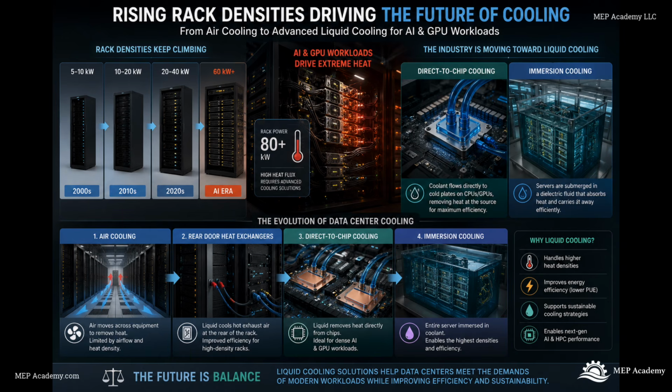But the key concept to understand is this. Air-cooled systems reject heat directly to outdoor air. Water-cooled systems reject heat through a water loop, usually using cooling towers and evaporation. Air-cooled systems are simpler and conserve water. Water-cooled systems are more efficient at large scale and better suited for very large cooling loads. Neither system is automatically better. The best solution depends on the project, the climate, the utility costs, the available water supply, and the long-term goals of the facility. Because in the end, every data center cooling system is trying to accomplish the same thing: move heat away from the servers as efficiently, reliably, and safely as possible.